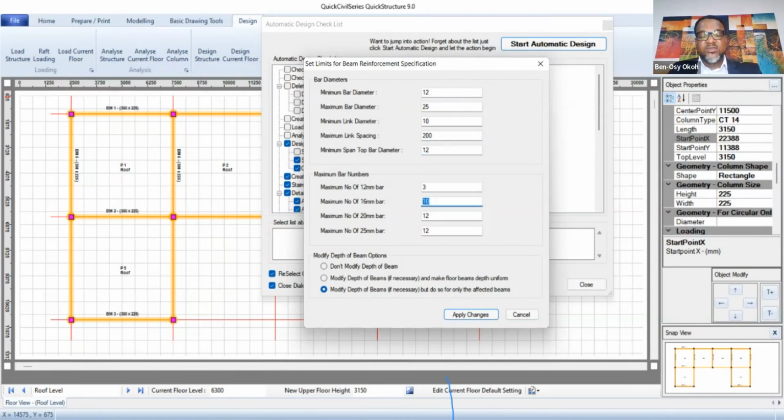Assuming we put 6 here, because when you are choosing the minimum number of size, another thing, that is where I say your experience in site comes to play. When you have a cluster of reinforcement, too many clusters of reinforcement, casting, the penetration of the aggregate becomes a problem.